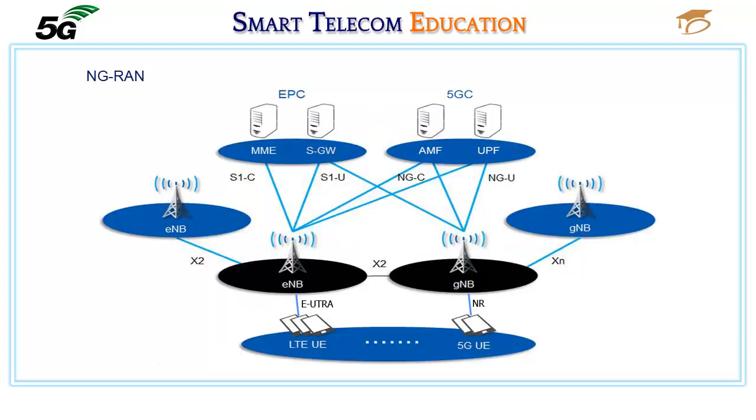The air interface between the gNodeB and user equipment, UE, has been named the new radio, NR. However, the interface between the NG eNodeB and UE remains the same as in LTE, Evolved Universal Terrestrial Radio Access, EUTRA. The gNodeBs and NG eNodeBs are connected to one another via the new Xn interface. The NR interface is designed to support multiple frequency ranges and bandwidths, low latency with flexible slots configuration, multi-gigabits per second data rates and increased spectral efficiency.